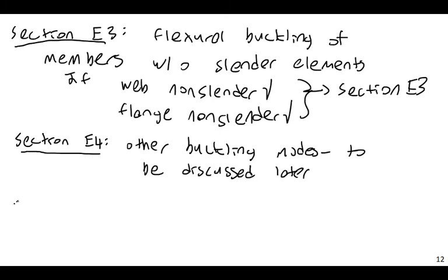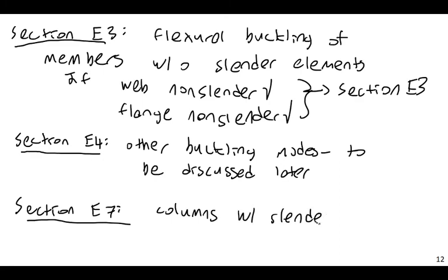But section E7, this is where you deal with slender elements. This is where you have buckling of members, columns, with slender elements. This is the section you go to.